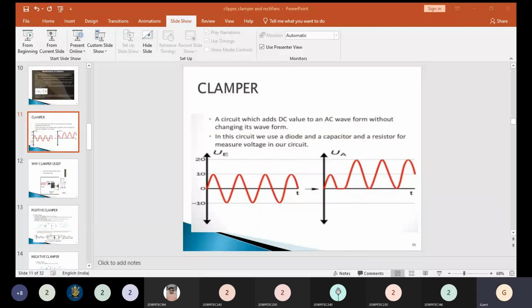It's a full wave rectifier. So from the options you are able to answer. See the options, no need to derive this one. This is a full wave rectifier. Compared with the half wave rectifier, all the values are doubled in the full wave rectifier, because in half wave you are using one diode and in full wave you are using two diodes. So definitely the VDC value is twice the output of half wave. So it is 2 Vm divided by pi.